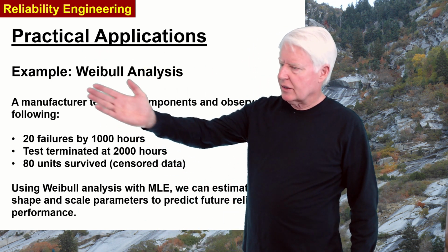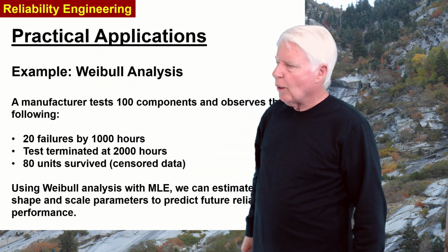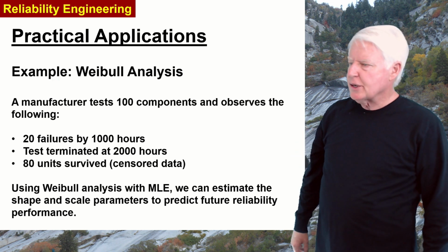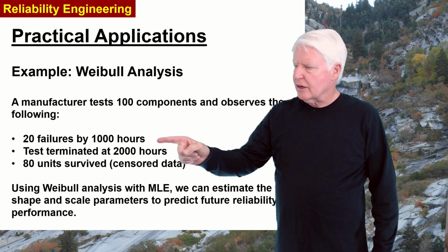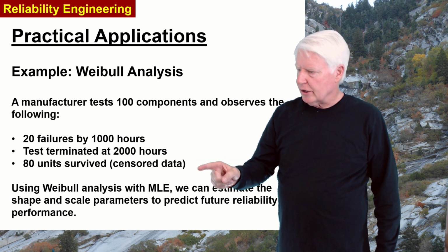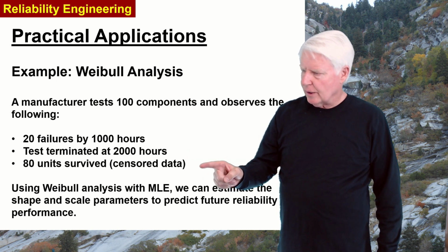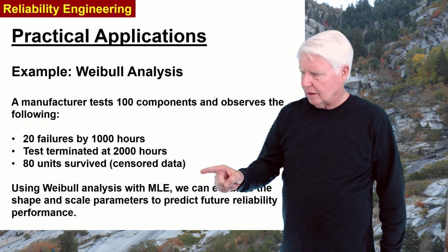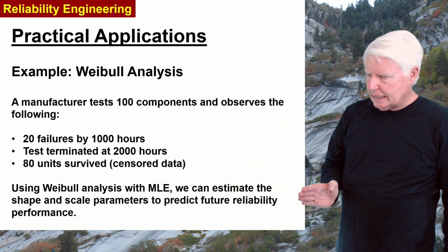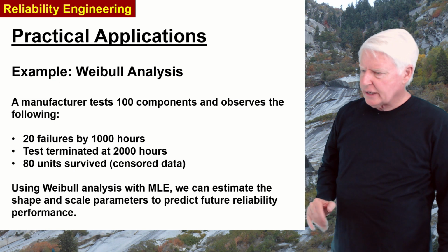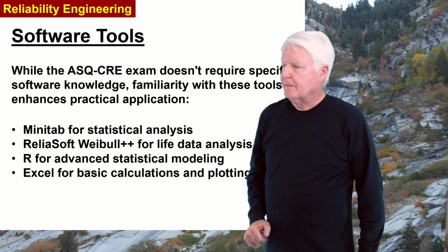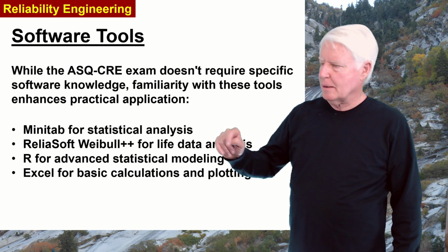Practical applications. Here's an example problem, Weibull analysis. A manufacturer tests 1,000 components and observes the following: 20 failures by 1,000 hours, test terminated at 2,000 hours, 80 units survived. So it is censored data because not all of them failed. Using the Weibull analysis with MLE, we can estimate the shape and scale parameters to predict future reliability performance. So there's a practical example.